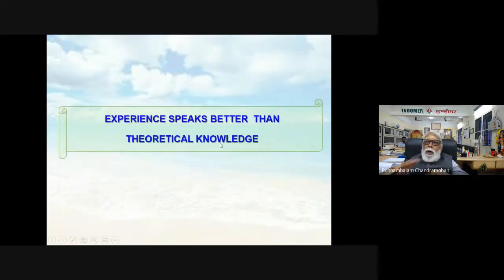And one very important thing: suppose there is a PhD student, he cannot just use the equation and say, I will use the same well-versed equation, and I got the wave record, and the transport in the month of March is this many cubic meters. It is not true. Here, everywhere, it is experience. The one which you estimate for one segment of the coastline may not be the same for another place. So littoral drift is mostly moderated by experienced oceanographers and coastal engineers, and they come out with the final figure. Theoretical knowledge will not help. Theoretical knowledge will tell what the direction of sediment transport is, but the quantum has to be defined by experience.